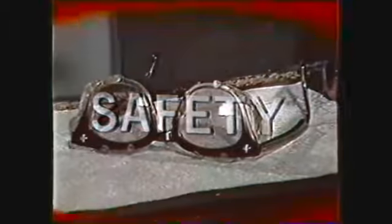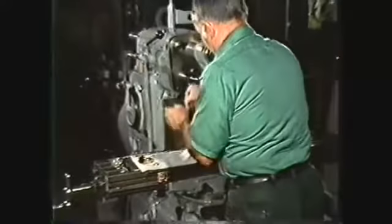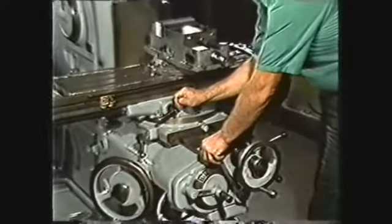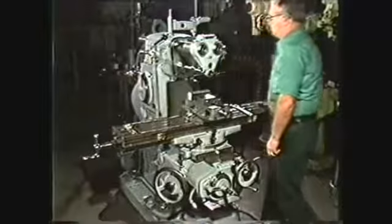Some of the safety precautions to be observed are: always put on your safety glasses, remove rings, watches, and other jewelry, keep sleeves rolled up above the elbows, never use the rapid traverse without first loosening the locking screws on the axis that is being moved, and never leave a running machine unattended.